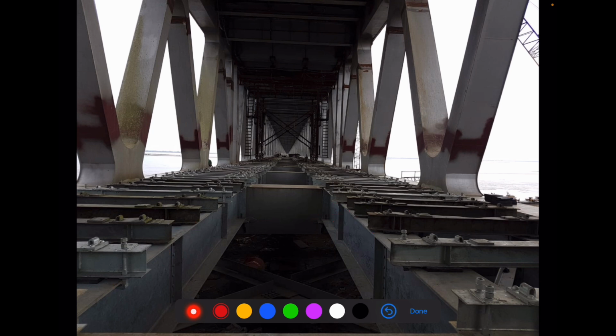Just for information's sake, I must tell you that these steel bridge sleepers are not kept directly over the stringer. There is a small rubber pad which is kept in between the steel sleeper and the top flange of the stringer. Why so? Because we want to avoid metal to metal contact.